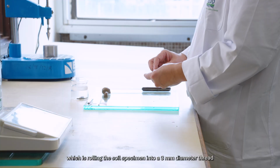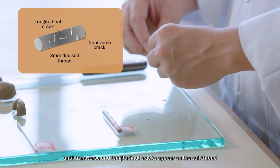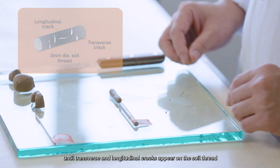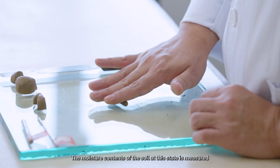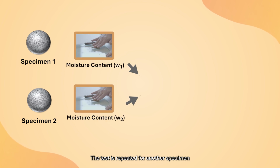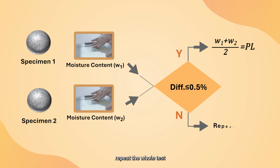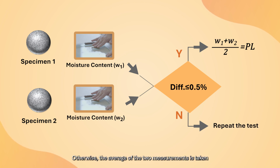which is rolling the soil specimen into a 3 mm diameter thread until transverse and longitudinal cracks appear on the soil thread. The moisture content of the soil at this stage is measured. The test is repeated for another specimen. If the two results differ by more than 0.5% moisture content, repeat the whole test. Otherwise, the average of the two measurements is taken as the plastic limit of the soil.